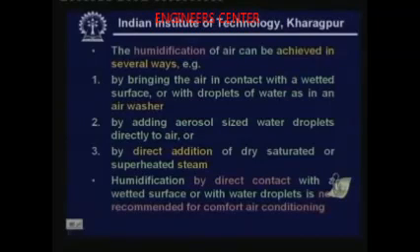Humidification by direct contact with wetted surface or with water droplets is not recommended for comfort conditions. This is for the same reasons which I have explained earlier, because whenever you are using a wetted surface, there is a possibility of microorganisms growing on the wetted surface, which may give rise to health problems. Okay. So in comfort air conditioning systems for winter, normally wetted surfaces or air washers are not used. Okay, air washers or wetted surfaces can be used for industrial air conditioning systems where human beings are not present. Okay, because of the health problems, right?